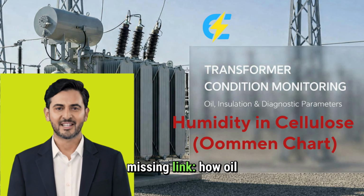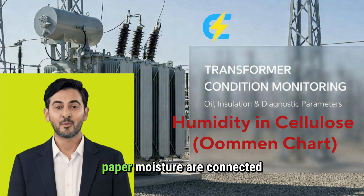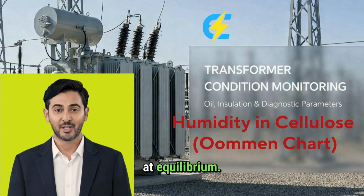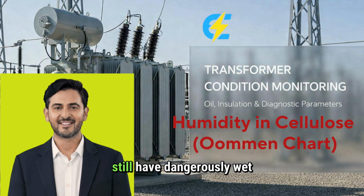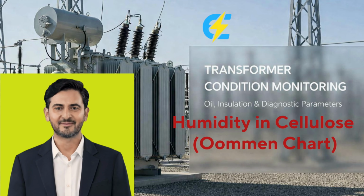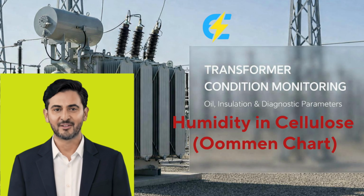It gives you the missing link. How oil moisture, oil temperature, and paper moisture are connected at equilibrium. A transformer can show acceptable oil moisture and still have dangerously wet paper. If you don't understand the Oommen chart, you are only seeing half the picture.